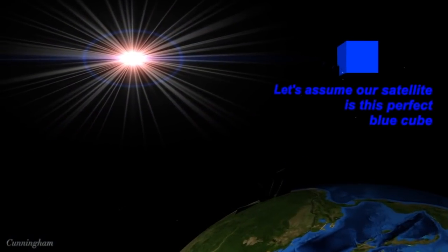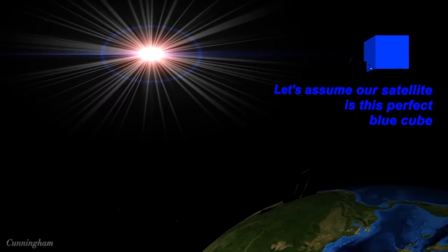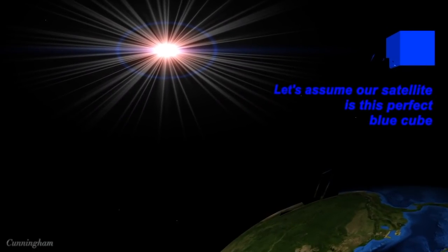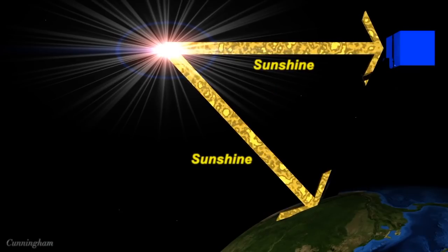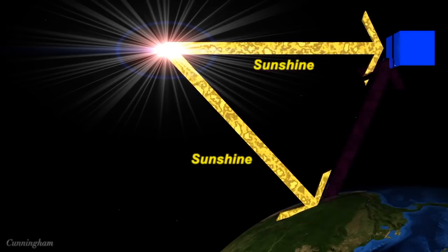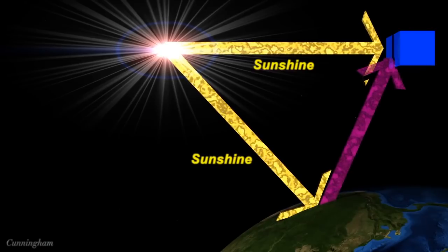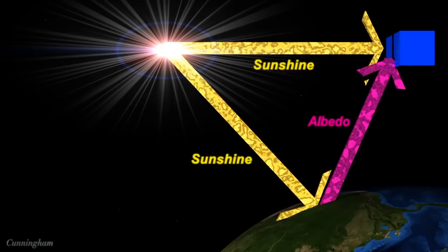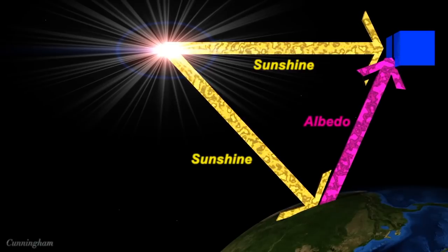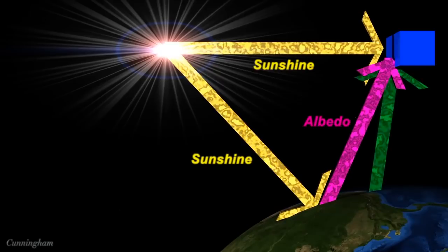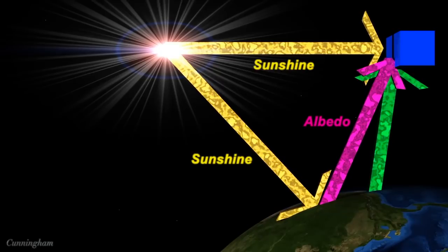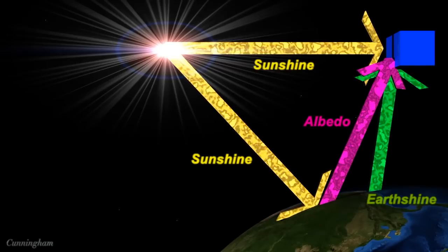Okay, so we have four major heat sources that we have to deal with in the space environment, and three of them are natural. You can see here the sun generates heat at about 1358 watts per square meter. And albedo, which is the sunlight that's reflected off of the Earth and strikes the spacecraft, is about 407 watts per square meter.